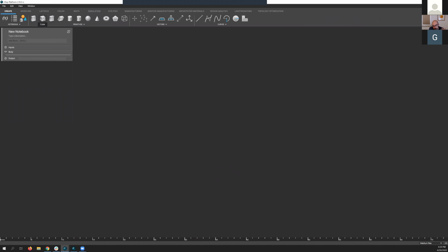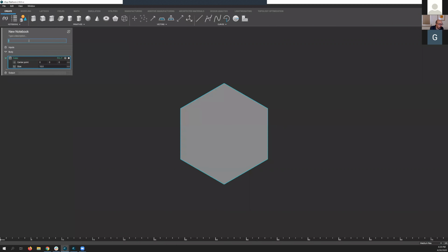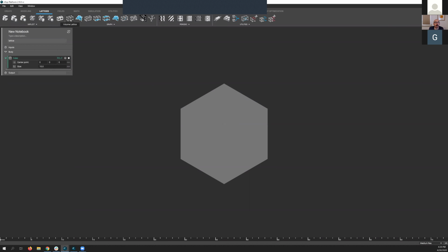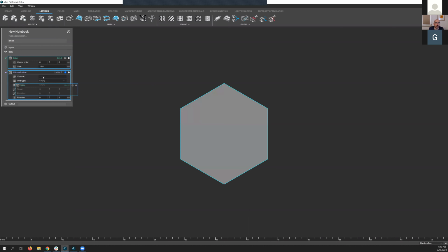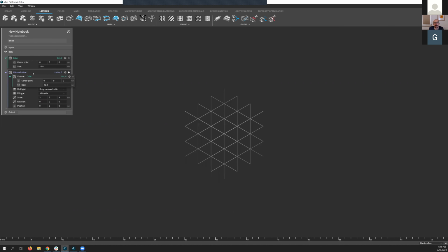So one of the things I was really excited about was the ability to start filtering out mesh entities. If we think about what happens when we generate a mesh for infilling a part with a lattice, let's take a look at that. So I'm going to generate a volume lattice, and I'm going to infill my cube here, and maybe I just go body center cubic. And let's go 3 by 3 by 3. All right, and let's thicken this up.